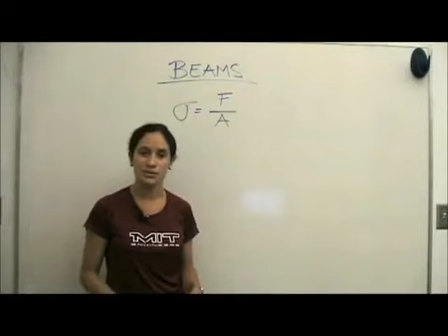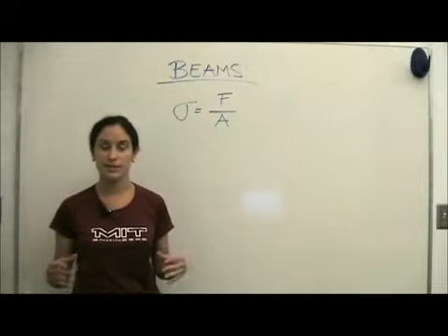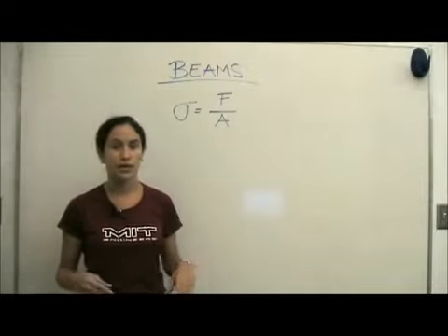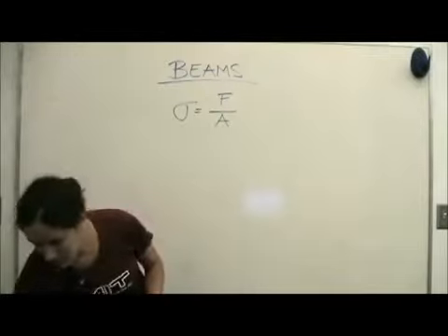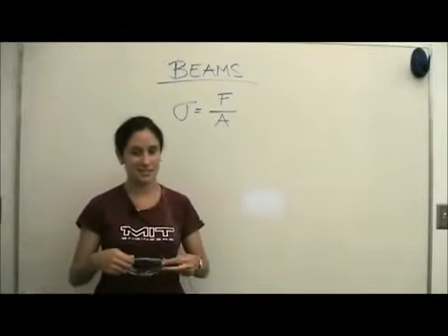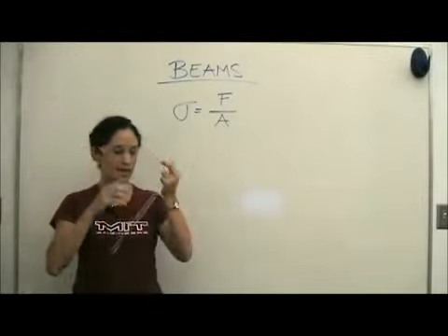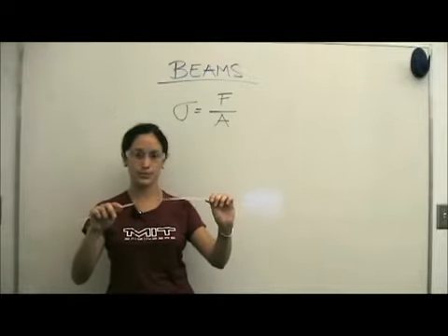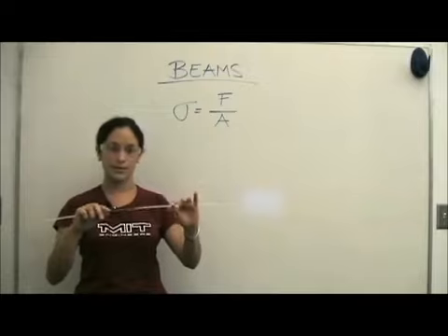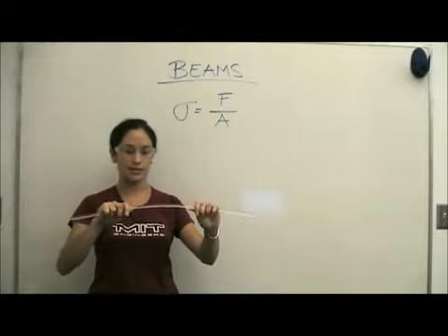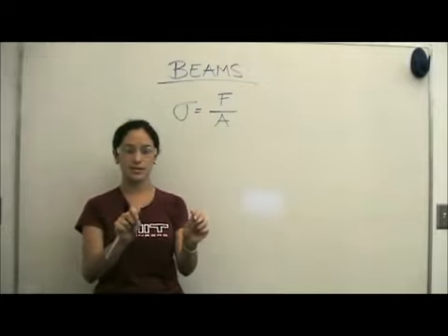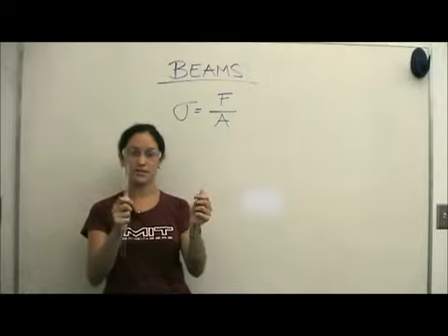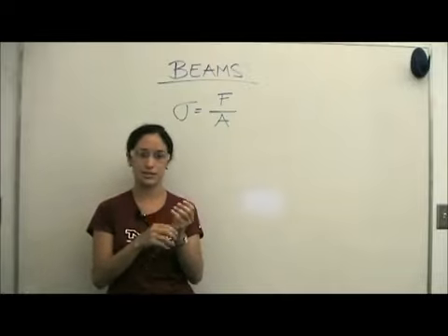An important thing to understand about stress is there's a maximum stress that things can take before they fail. We're going to use a plastic beam to demonstrate this. I'm going to use safety glasses just in case. We have a plastic beam here. As I load it, we can see that the beam deforms. The stress has been low enough that the beam has not failed. However, if I keep loading it, there's going to come a point where the beam fails. The stress was too high and the beam fractured.